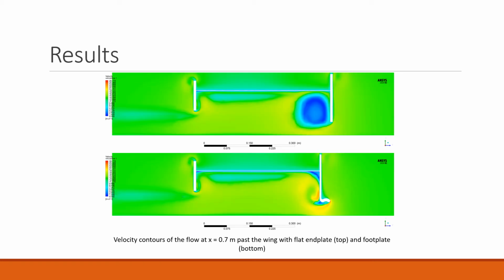The velocity contour at the trailing edge of the flap shows the vortex in the end plate with the flat wing has already begun to break up, disturbing the airflow around the underside of the flap. The vortex has developed inside the channel and spilled under the wing, however, its center is farther from the wing and it therefore has much less effect on the flow around the wing.